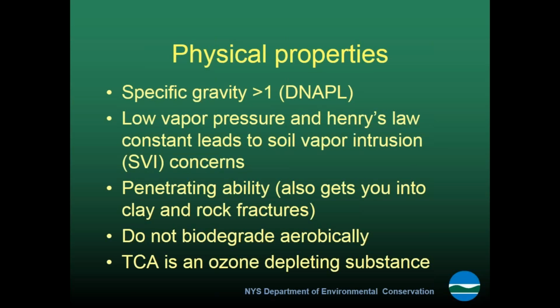These chemicals also do not degrade aerobically. We weren't aware of any way that these degraded biologically until, I believe, it was a military base on Cape Cod, where they were chasing a plume of TCE, and it went underneath the landfill, and when they went to look at it on the other side of the landfill, it was gone. There was some part of it passing by the landfill to the side, but clearly something was going on under the landfill that was degrading that TCE plume.